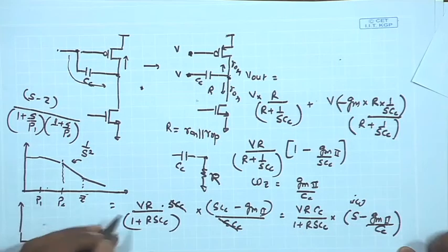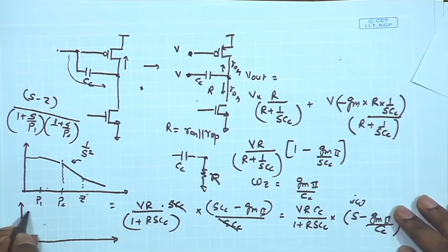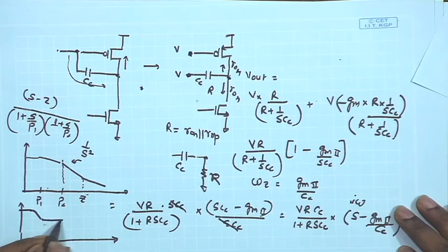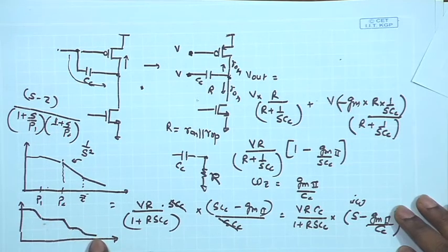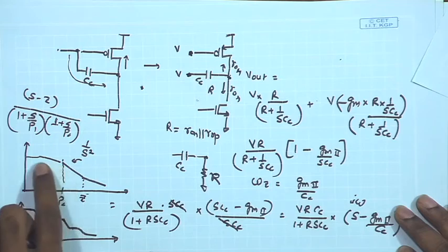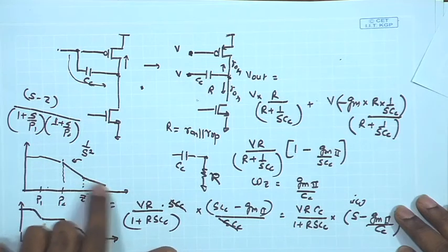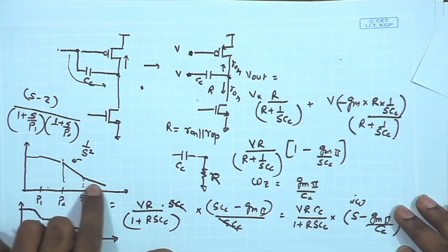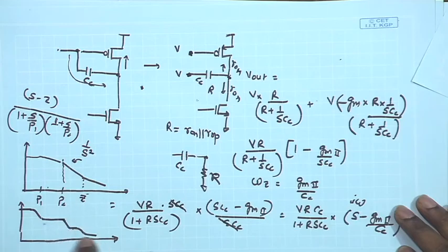As a result, we are having an overall phase which will basically approach 180 degrees much faster because of the 0, because it is going to make it all the more negative. So, you are having further phase degradation, and it is also degrading the slope. So, the slope of the decay of the gain has been reduced and the phase is degrading further.